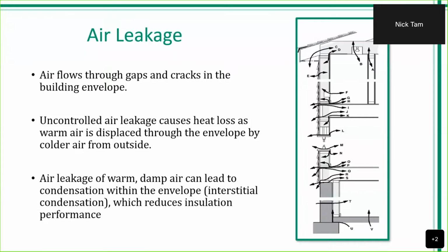What happens is any conditioned space on our interior side is going to be displaced by the conditions on the outside of our structure. In this example, if you take a cold climate, we have a heated interior space. With any type of air leakage, especially in excess, that warm air is going to be displaced by the cold air on the outside, and we have our HVAC systems having to continuously run. It has to be noted that any HVAC system conditioning our interior space has a lifespan of its own. If it's continuously running, trying to maintain that interior space condition, we're decreasing its lifespan. And more importantly, we're also increasing energy costs.